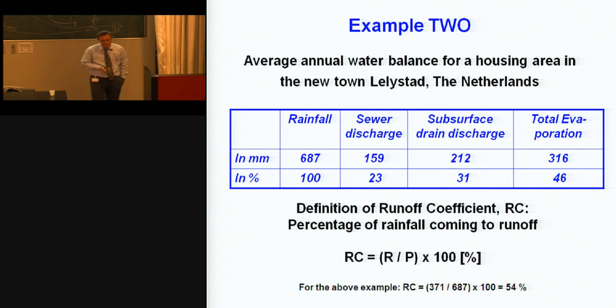In case of flash floods, all the rainfall is converted to runoff, so the coefficient will be maybe around 90 or 80. On short time scales, for small localized areas with flash floods, it can be almost 100%, yes. Or if you have hard rainfall on big sealed, impervious areas like a big parking lot, there's almost no loss, so it's close to 100%. But on long-term average, for larger areas, no, because a lot of water is then also infiltrating.